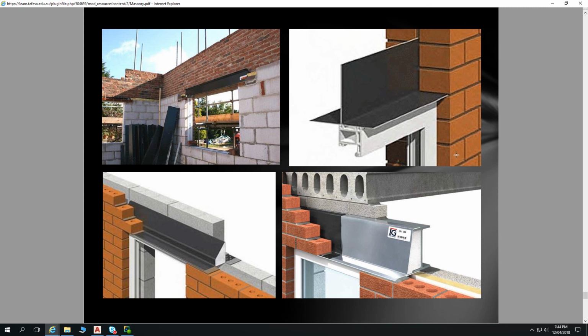This one here is not only carrying the brickwork, but it's carrying a suspended floor as well. That's a Delta Core flooring system, a hollow core concrete slab system. We've got an I-beam over here going down to some load-bearing structure, I assume. That's taking the weight of this, but then we've got a thick flashing over there that's strong enough to support the brickwork.